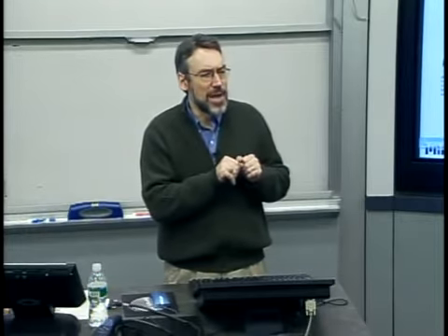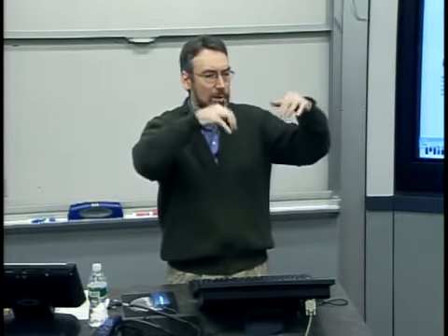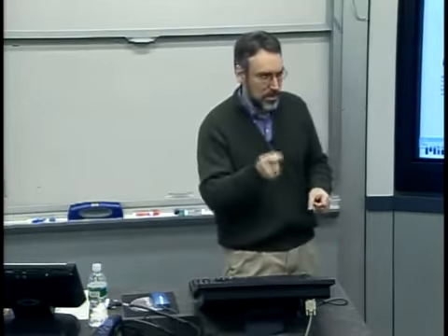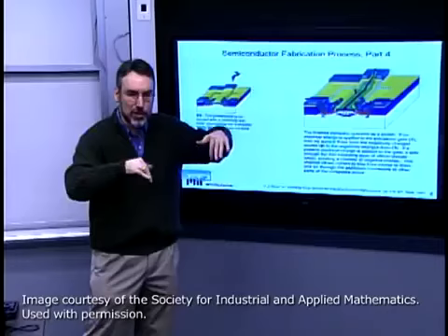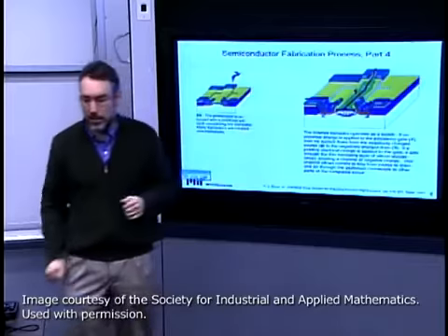At that coarse level of 3D, I would say several memory chip makers are already doing sort of chip stacking within one package. So in some of the memory chips, if you were to etch away the black packaging and casing around one of those chips, you might find a stacking, but they are not heavily electrically interconnected. It's not a fully integrated structure. In fact, at the end of the day, they typically have bond wires, big macroscopic wires coming in the sides of the chip separately at each of the stacking.